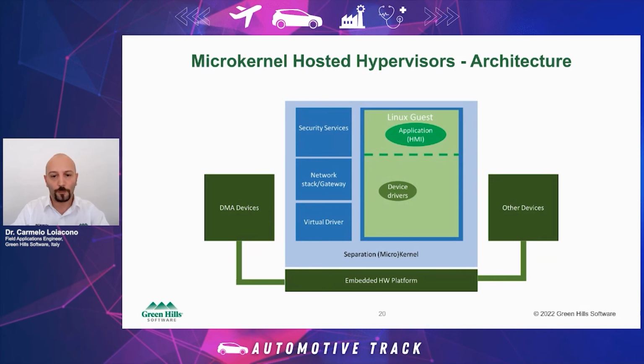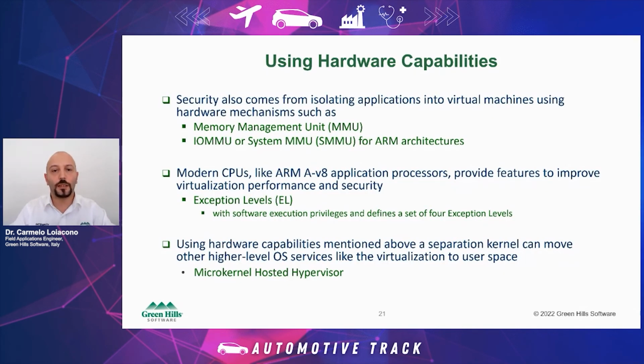the security. The separation microkernel also needs to use the hardware capabilities that are available today, like the memory management unit and the I/O memory management unit, which is the second stage memory management unit, where we can also protect the devices, the peripherals. So the access to the peripherals with the IOMMU is protected.